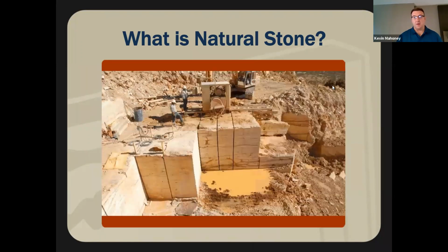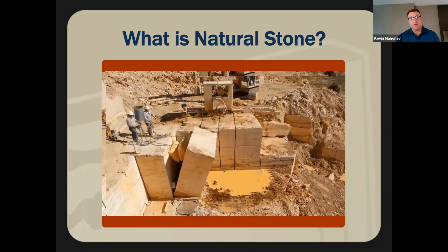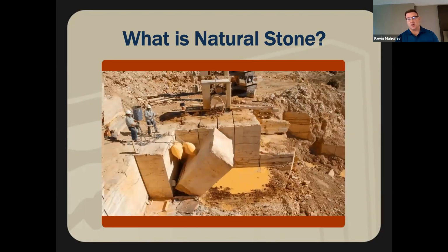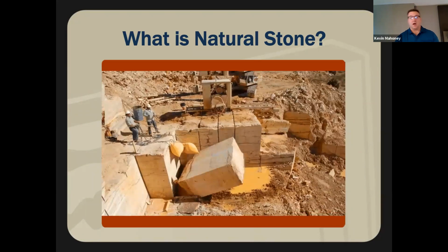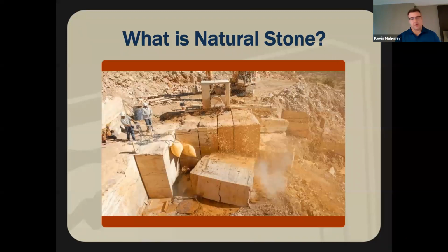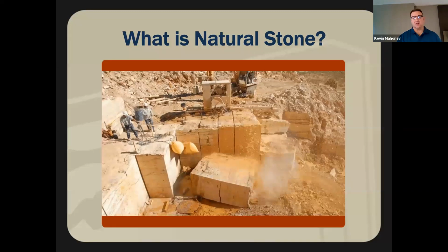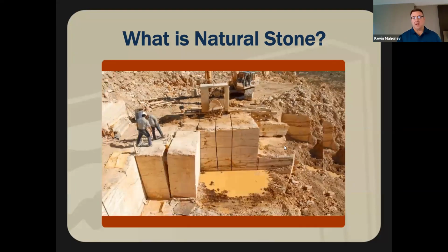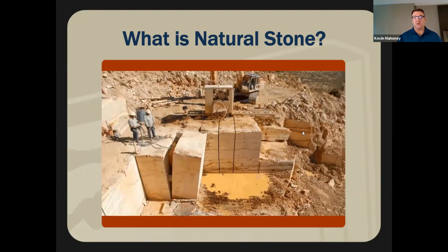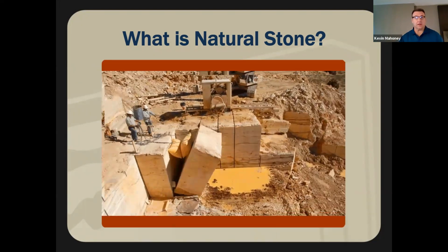Here is a travertine being harvested, a big block. You can see the airbags are actually pushing this thing out. You can see the sediment layers in the stone, and it's actually being separated down through the veins, but you can also see when it hits the ground that it actually cracks with the grains as well. Just an important thing to notice when we're talking about the structure of stone and how stones are constructed and how we cut them and utilize them for different products. So I just point that out. It's cool. You can see how big the block is. Those aren't tiny men. They're actually life size.